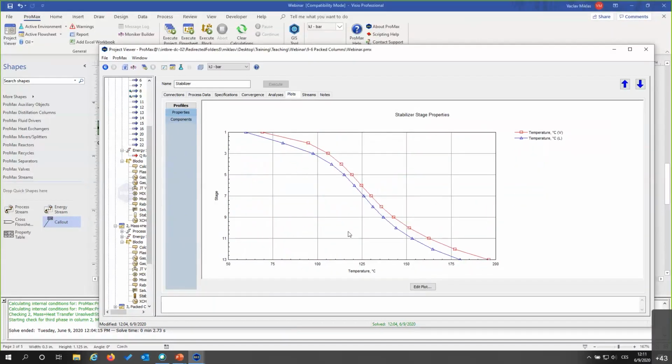And as I mentioned, if there is some tray where you see a super steep curve, then for instance, the vapor plug flow option might be good. But in most of the cases, the well mixed, first of all, is the most conservative option. And second of all, I haven't really seen the other used too often. So this is just something to note.